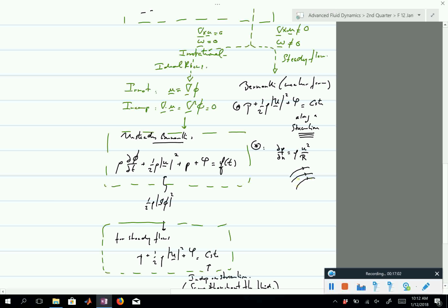Okay, and I remember the sign. If you have a flow that is bending in this direction, for instance, right, you know that along a streamline you can impose the Bernoulli equation in that particular case. But if you want to know how the pressure varies across streamlines, how do you know where the pressure is higher? Is it higher on the top or higher here? On the top, right? So the pressure would be higher here and slightly lower here. That's because the flow is bent.